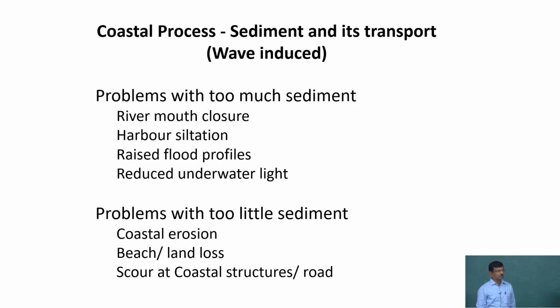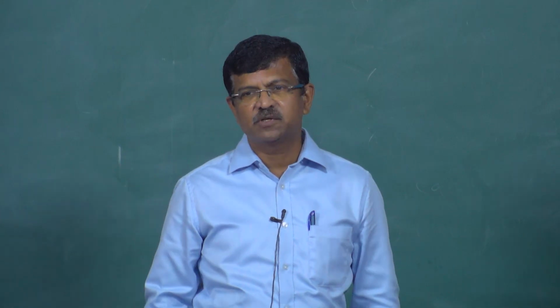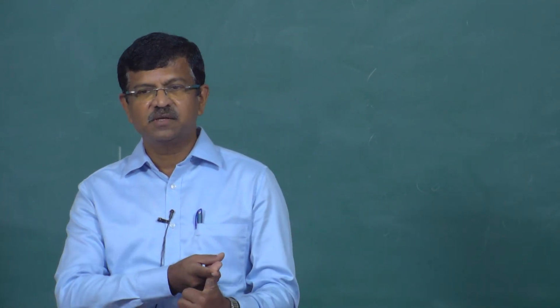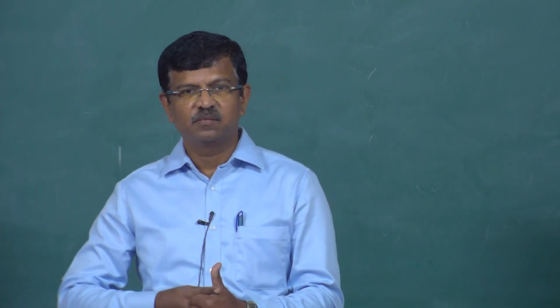From the engineering perspective, whether it is too much sediment or too little sediment, a sediment-starved coast or a sediment-surplus coast, both have their own pros and cons. I cannot say sediment deposition is always good. All of you have in mind that sediment erosion is not good, but sediment deposition is also not good, because deposition along the river mouth reduces the flow across the river.